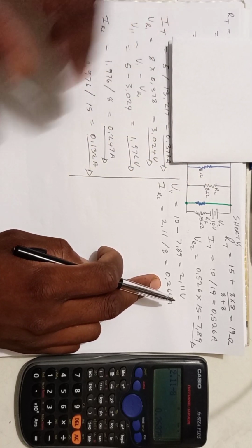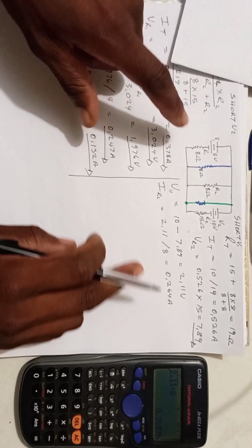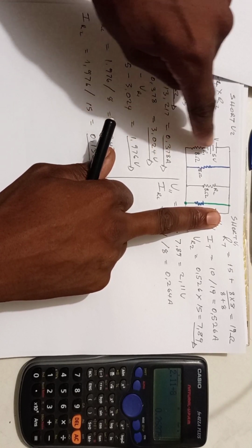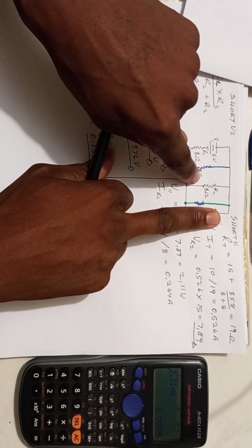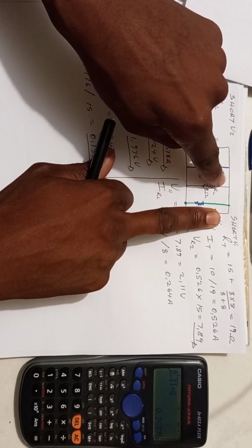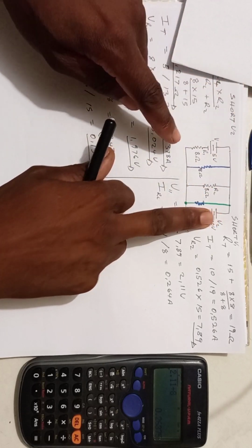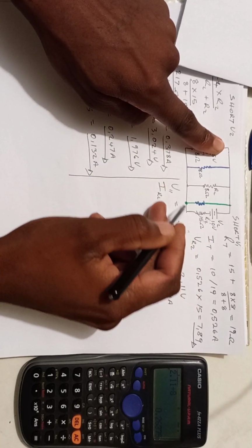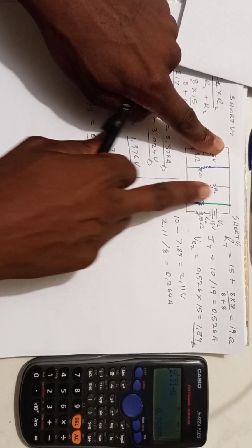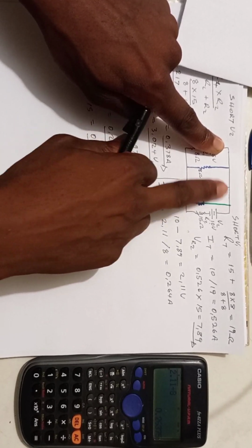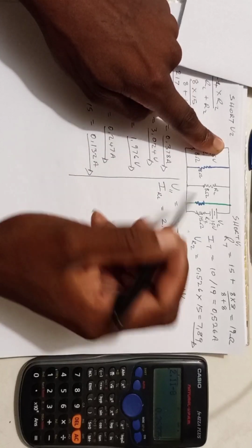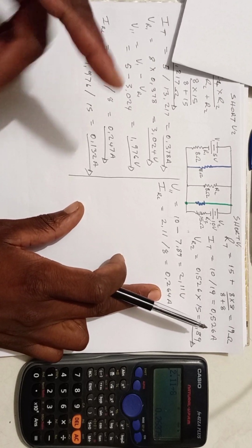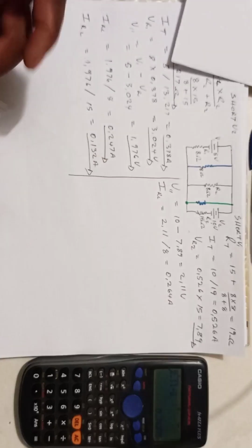We would stop here if we were only asked to calculate that current. But now we take these currents and add them. The reason is, when these batteries are like this, we know that when we short this one, electrons will flow in this direction. So the direction of the current will be up on RL. And again, when we short this one, we've got negative here. Electrons flow this direction, and the direction for the electron flow will still be up. So we will be adding these currents to get the current that we are asked to calculate for this circuit.